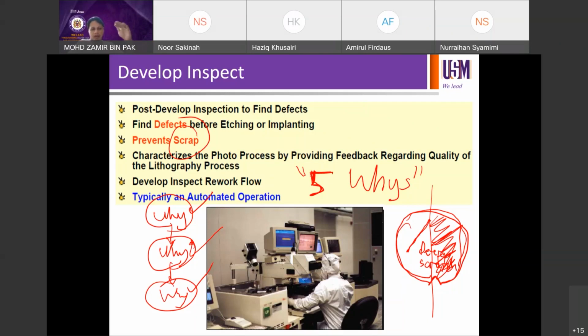Is it some friction or movement or the belting? Okay, the theta of the robot arm uses a belt, like cars use belts. So sometimes the belt is worn out or torn, or for some reason it's premature damage, and then it goes back to the whole configuration around the robot arms. Okay, sometimes a screw is loose, the technician did PM and didn't tighten the screw back properly. So there are thousands of different potential root causes.